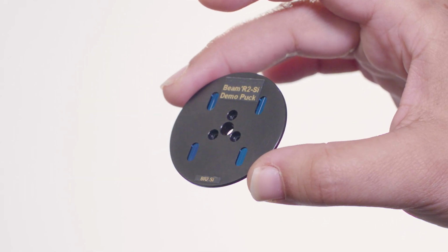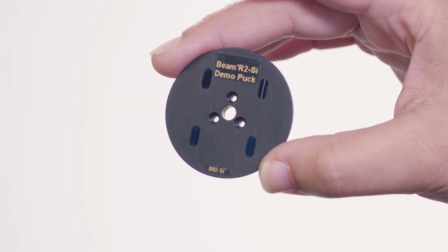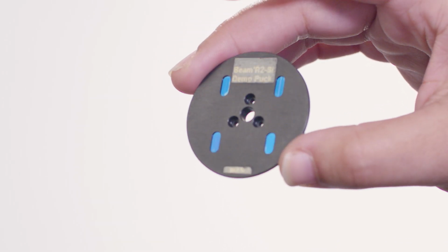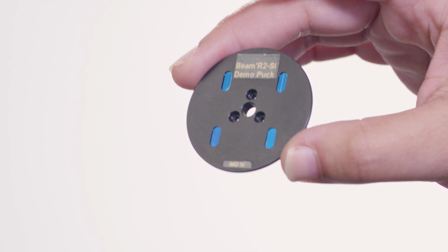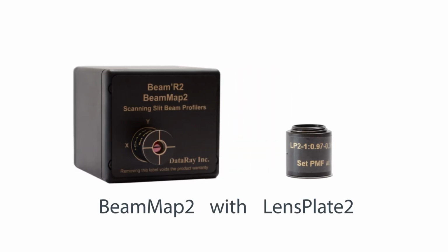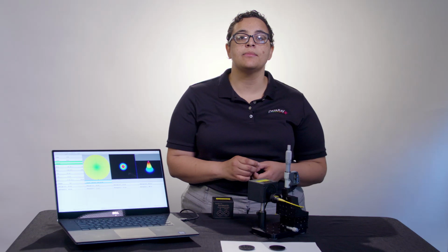In addition to the BeamMap2, we also offer the BeamR2, a single-plane scanning slit profiler with the true 2D thin sapphire scanning slits. BeamMap2 can be paired with a number of accessories, including our Lens Plate 2, which can re-image inaccessible beam waists, magnify beam waists which are too small for accurate measurements, or focus a collimated beam to allow for m² measurements.